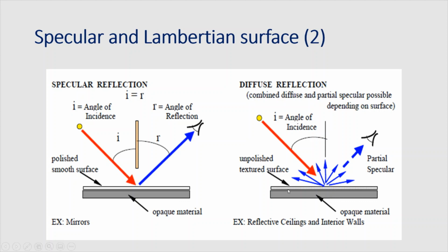Of course, only on the upper hemisphere, because this surface is opaque, so we don't have any transmission coefficient. So no matter where you are placing yourself to watch this particular flux, you can stay in every single position of the upper hemisphere and you will see something that is reflected. All right? This is very, very important.